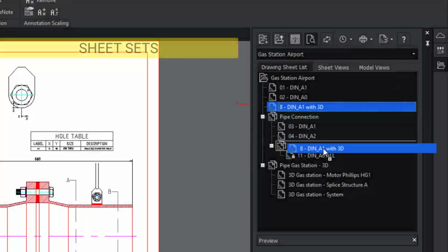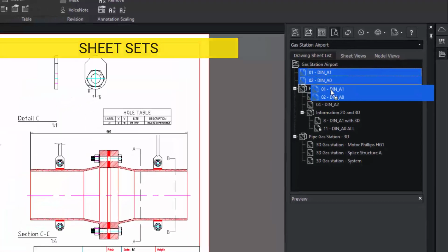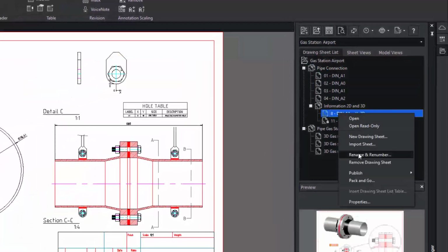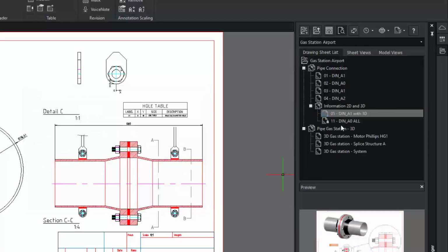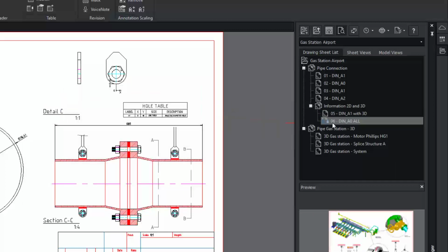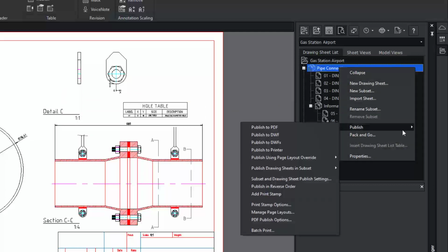Finally, creating layouts will also enable you to use sheet sets. The advantage would be to configure sheets coming from different drawings, and even different users. It helps to organize your project with groups of sheets by topic. When you open your sheet set, you can see the entire project at once and keep it always ready to print, although multiple drawings are required.